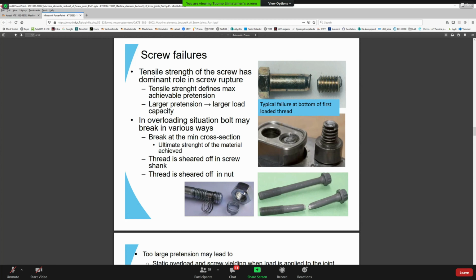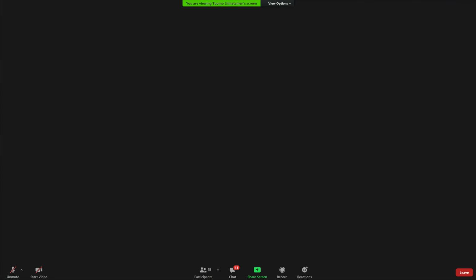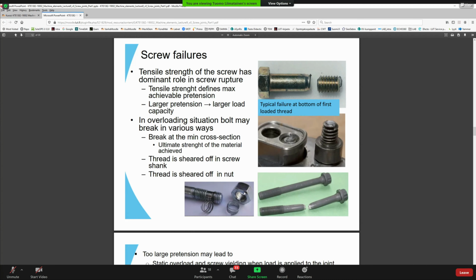So probably the best one is the one with the least secondary consequences. Yeah, the best one would be probably that the green bolt shears the head off and does not break in the middle, so that the pin would be in place, but it wouldn't have any pressure on it anymore, so that would be the only loss.